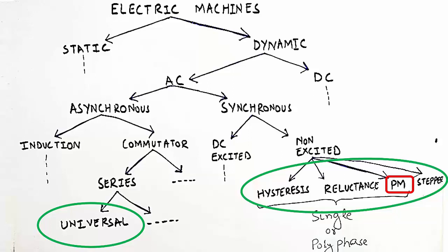While the purpose of stator winding is solely to produce a rotating magnetic field, under the influence of which the rotor has to rotate, it is not important whether this rotating field is achieved by single phase, two phase or three phase. Nevertheless, one thing that can be argued is that we switch to higher phases when larger load is to be handled, while these motors are designed to handle fractional or subfractional load, which can easily be achieved by incorporating single phase windings on the stator.